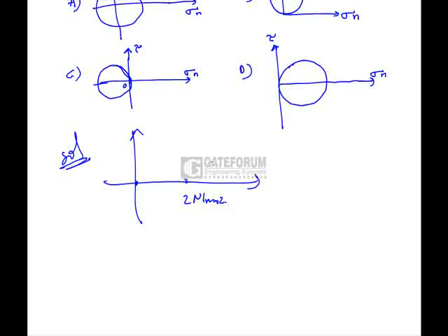For the Mohr circle, now take the center between these 2 points and draw a circle. Let us say this is O and this is A. OA as the radius and the midpoint of OA as the center, draw a circle which gives the Mohr circle for the given stress condition, that is, in the options D is the right answer.